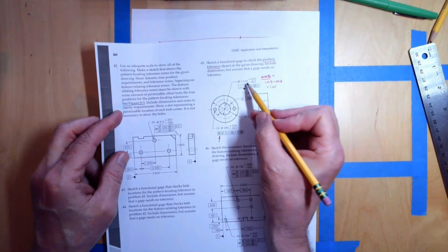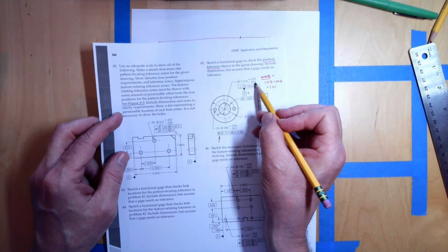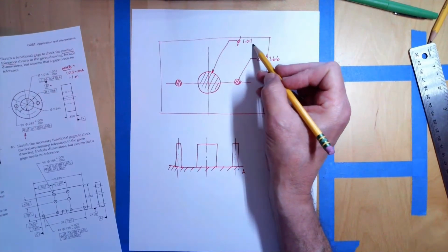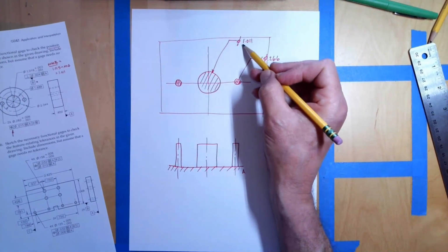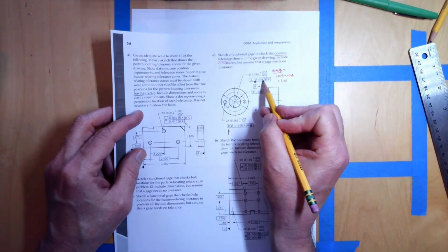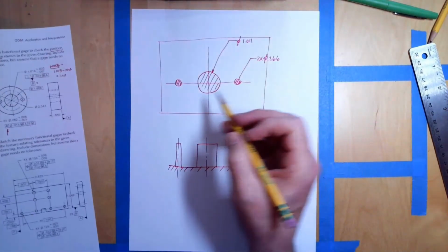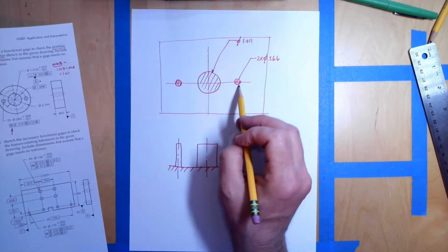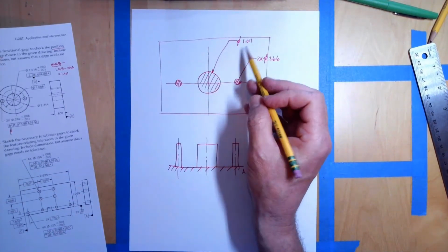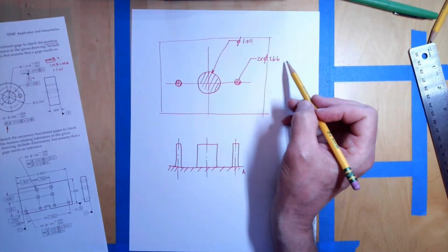Well, that should work, right? If the hole size doesn't get less than 1.015, right? 1.016 minus 1 is 1.015, then it should be able to fit on a pin that's a size of 1.011. Bear in mind that we also have 4 thou at MMC of perpendicularity that we can play around with. All right. So in order to check now these two holes on the side, we're going to have this pin 1.011 and these 2 pins of 266.